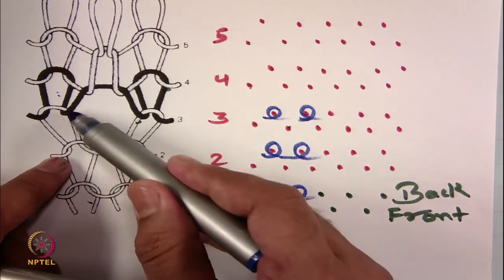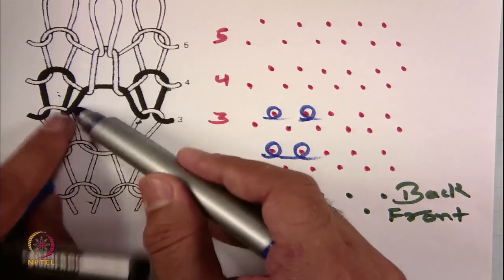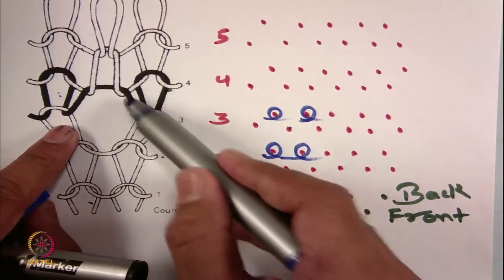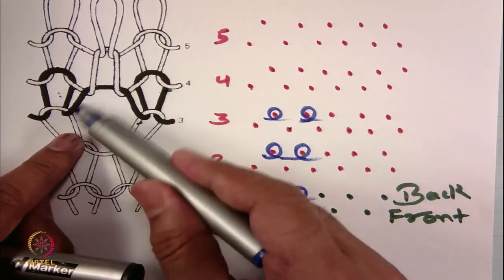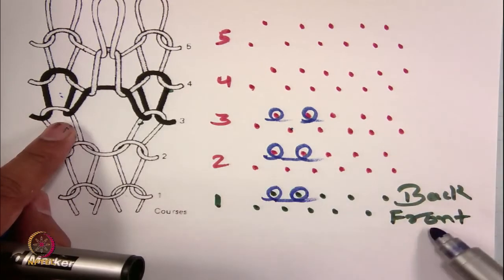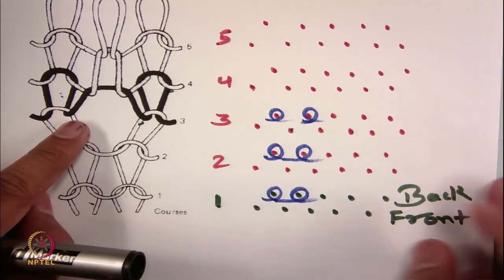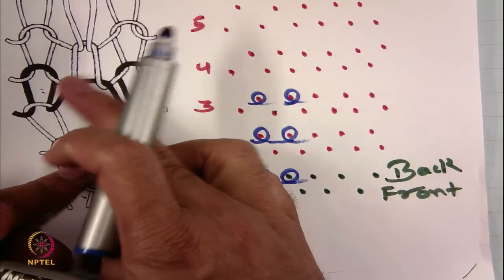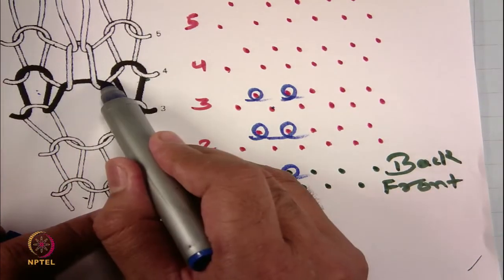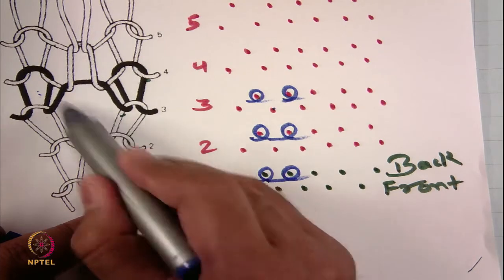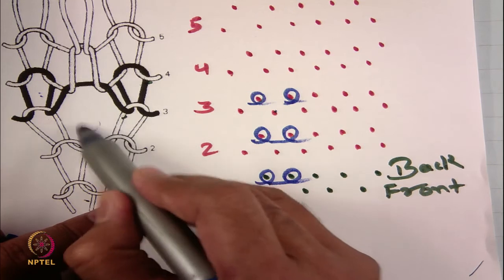So, this is the old loop. You can see the nature of the leg is towards the front. On the front side the leg is visible. That is why this particular loop has to be created using the front bed. So, one of the needles has to be used. Now, the question here is, if you carefully see this particular loop, 2 intermeshing points are missing, and at this particular loop there is no old loop on the front bed.